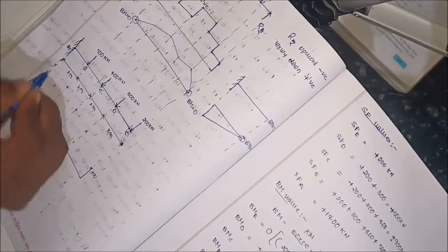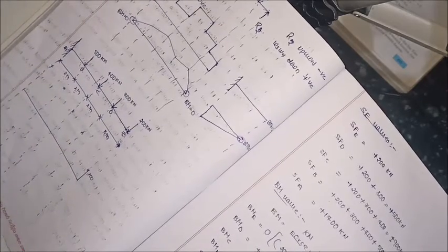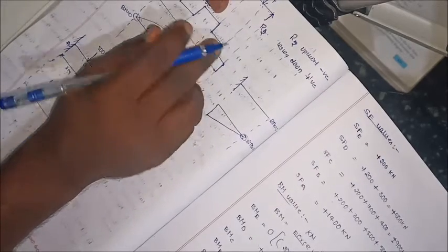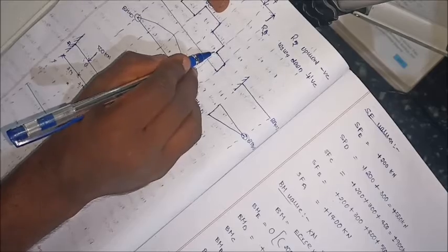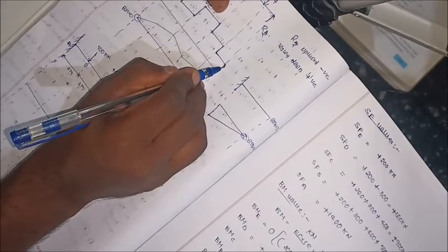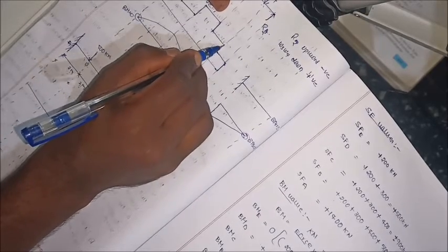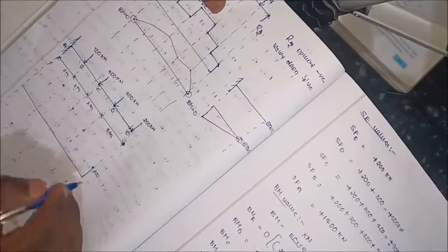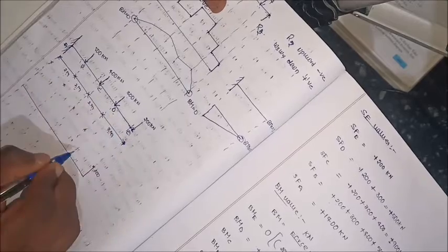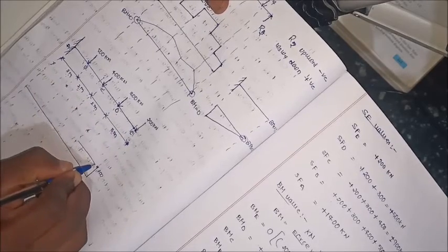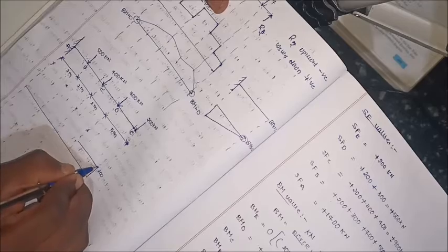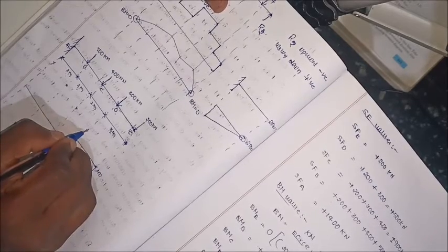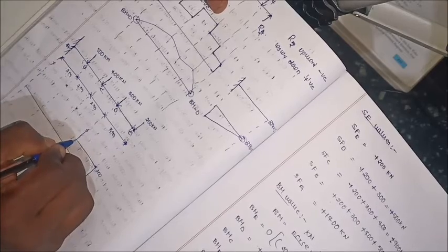You already know the shear force diagram between 2 point loads is constant, and the rise or fall occurs at the application of loads. So between these 2 point loads it is a constant straight line, and due to the increasing value, the shear force diagram rises.